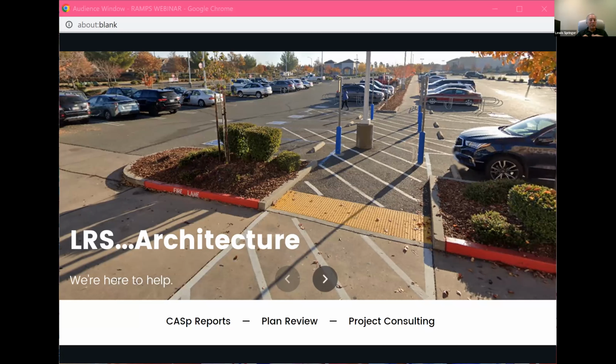And so that concludes it, but this is also a great slide. I was going through and it's like, so here we have an island, but the island only has detectable warning on one side. Imagine if you're visually impaired and you're coming down the accessible route, that accessible route goes out to the public way. You come down a curb ramp, which has no detectable warning, which it should. That detectable warning would let you know that you're entering a vehicular area. The vehicular area, then you come across and you would actually want to hit detectable warning on the other side of that landing, have a 24-inch strip in the middle, and then detectable warning again before you hit the drive aisle. Now that would be the old solution.